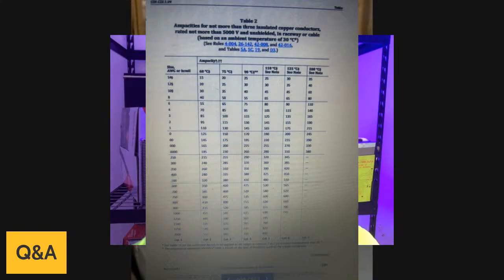So we're going to head over to the, let's see here. So again, under the OESC, a standard 200 amp single phase residential service requires checking your termination temperature readings. Typical 75 degrees Celsius, copper conductors under Table 2.